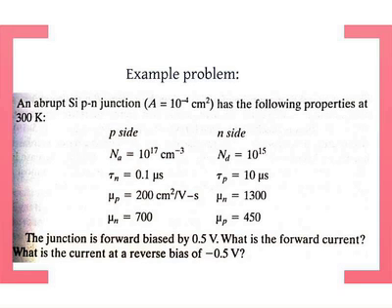You know this part. This thing, Np, is the same way. You have Ni squared divided by Pp, which is the majority carrier concentration of the holes in the p-type, which is the acceptor concentration pretty much. Okay, so also need this. Now you need these things. These are material constants, and you just look them up. I mean, you can look up the ways to calculate it, but here they do it with the Einstein relations, remember, because mobility is given. You can calculate the diffusion coefficients. The ratio of diffusion coefficient to mobility is given by kT over Q.